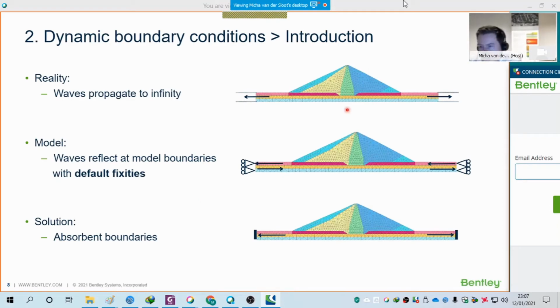So say that we have our bedrock motion. Let's assume we have the bottom here as bedrock. So this light blue area is bedrock. Otherwise, we cannot model such a shallow model anyway in finite elements. Then we have to extend it deeper. But let's say we assume that this bottom is a bedrock. The best way to model this is to have the bedrock signal applied at the base, which is within the bedrock, and then also include a transition from bedrock to the softer soils.